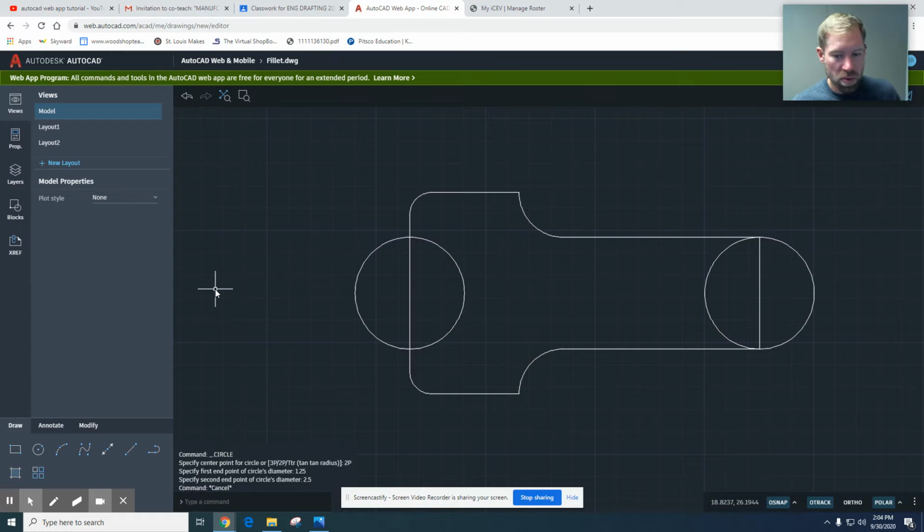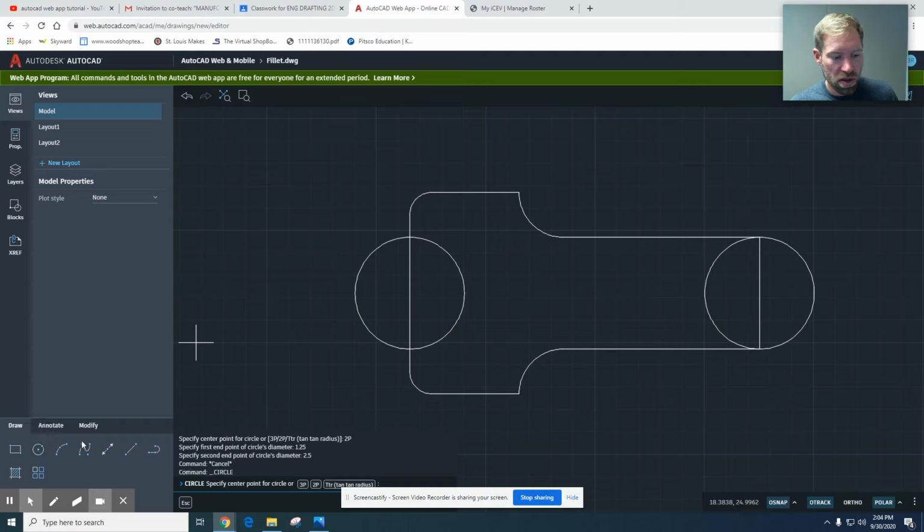Now we are looking more like our shape we want. So there's a few more pieces that we need to do before we get there. So let's locate this middle slot right here. And the way I want to draw that middle slot is I want to locate some circles again and snap some lines to form that, and then trim out the inside.